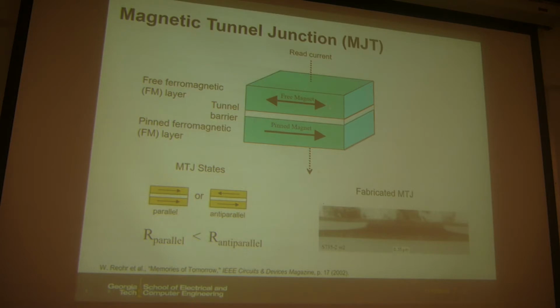But in this design, we are going to fix the pinned layer. The magnet orientation is always to the right by design. And then the free layer on the top, we can change the orientation of the magnet by different mechanisms we will talk about later. That's how we differentiate Field-MRAM, STT MRAM, and SOT MRAM. So basically the difference is how you change the top free layer. What mechanism you use will determine the type of the MRAM.